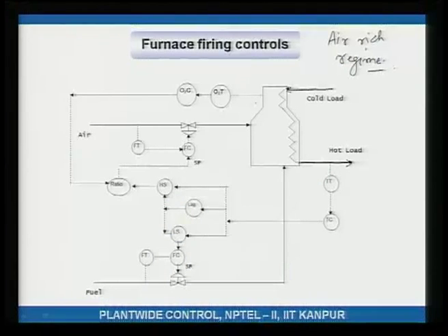Once the fuel gets into the furnace, it must be ensured that whatever fuel enters the furnace, it burns. If it does not burn, that fuel will accumulate inside the furnace. Next time around, when you start putting in air, you think that there is no fuel there, but there is unburnt fuel left over from previous operation inside, and you can have a blast. Okay.